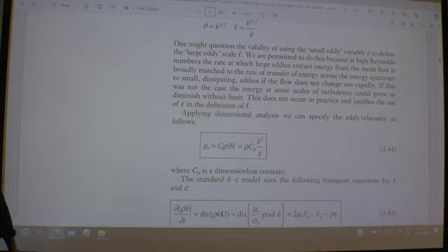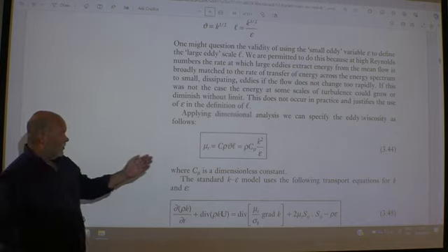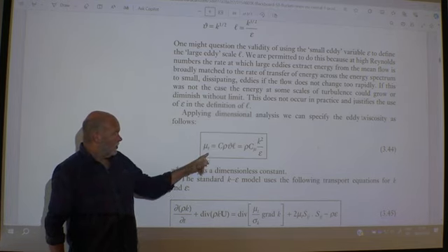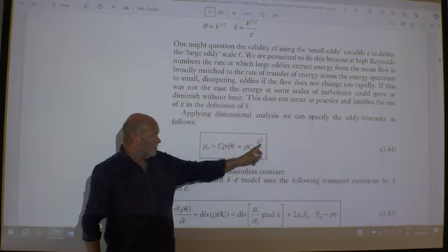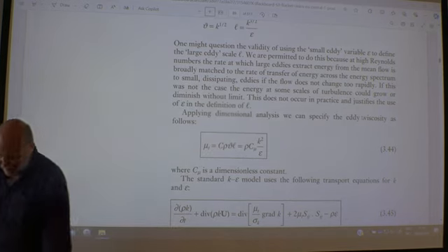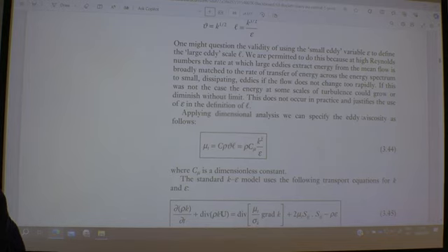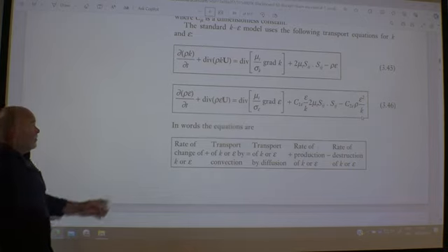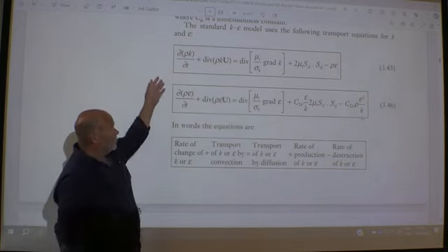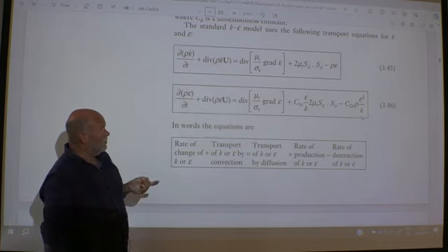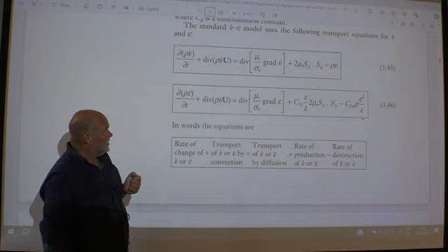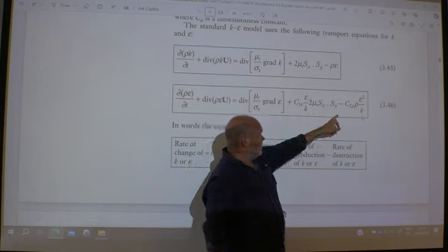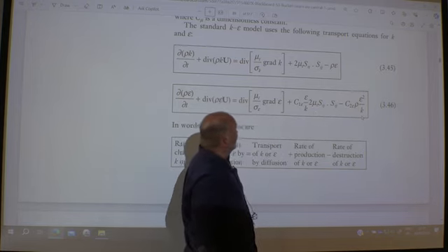So here you have the Prandtl-Kolmogorov equation, the last coupling needed, finding the eddy viscosity based on K and epsilon. And then here you see examples of such model transport equations, how they can be derived. And yeah, the different constants here have to be played around with.